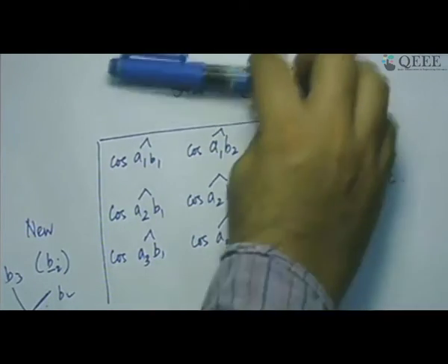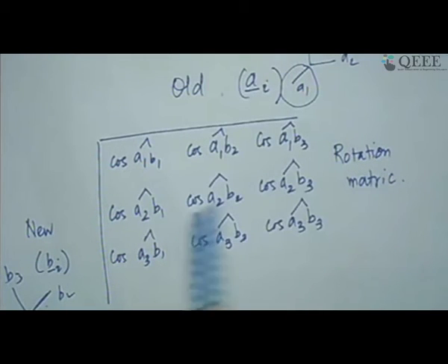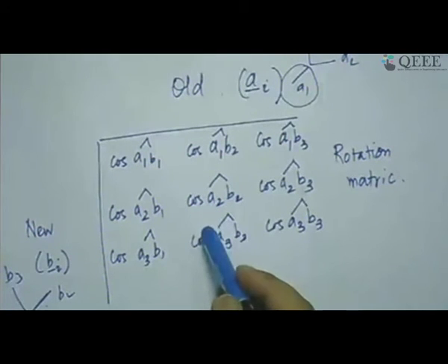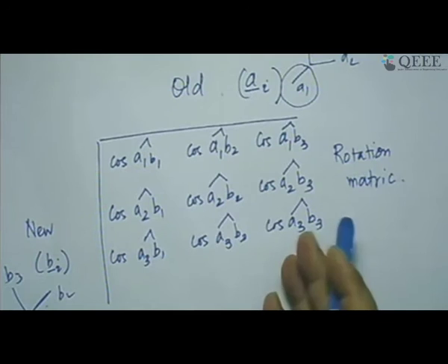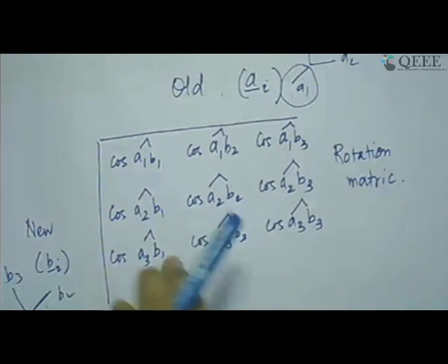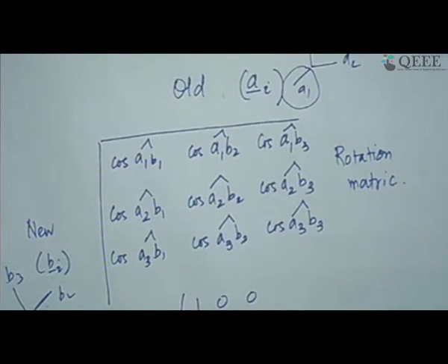And if you have the rotation matrix, as you can see, the rotation matrix consists of only direction cosines, and then we use the property from trigonometry that cos 90 plus theta or cos 90 minus theta has some relationship to sin theta. That is how the rotation matrices are typically written, right? The rotation matrix is 1 0 0, 0 cos theta sin theta, 0 minus sin theta cos theta. There is sometimes confusion whether the minus sign is here or here. So it depends on the way the theta is defined, the way the rotation is done.